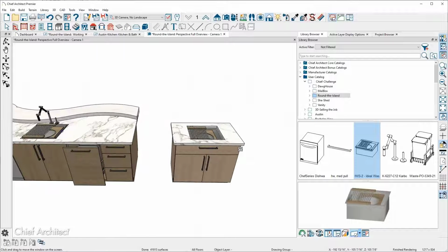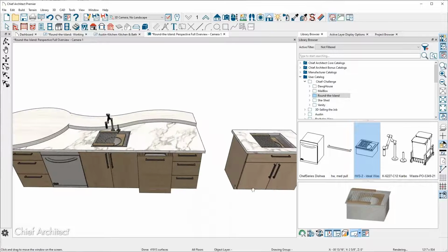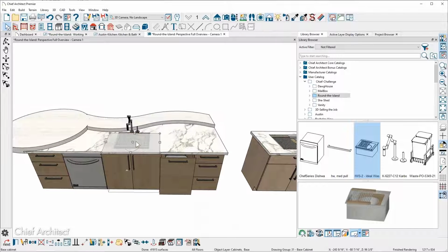So when you have an automatic countertop, the sink goes in there, it has an offset in the symbol itself. In this case, it's typically the countertop thickness, 1.5 inches. Since in this project I didn't actually use the countertop, the sink was actually too low by the countertop thickness since I drew that independently. So all I did in that case was click on the sink itself, and you might have to press the tab key to actually get that selection.